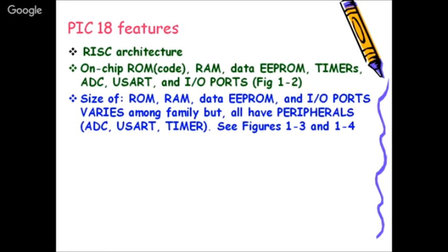Because of the inherent capabilities. And RAM also, once again, in case of 8051, RAM के केस में कितना हमारा होता है, 128 बाइट्स, 256 बाइट. So maximum, Intel's is 128 bytes in 8051, and Atmel's gives 256. And mostly these 128 bytes are consumed by your special function registers, which are mainly used for controlling your on-chip peripherals like timer, counter, serial ports, etc.